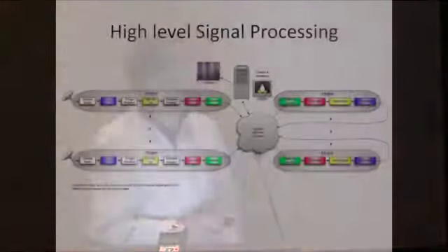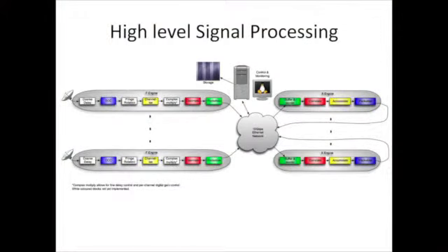What is the signal processing that needs to happen there? And again, I don't want to go into any detail. You probably can't see the detail. But basically, we get signals back from an antenna. That is processed, and in our case, our correlator is an FX correlator, which means we do channelization first. We break it up into frequency channels first, and then we do the correlation or the cross-multiplying of those channels. So those signals come in directly to a processing engine here, which performs that first part of the algorithm. And then we distribute that signal via a 10 or a 40 or a 100 gigabit Ethernet network to the second part of the processing, which is the X engine.